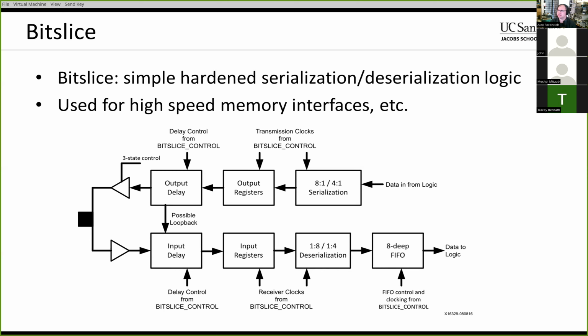This logic is really intended more for things like high-speed memory interfaces, things like DDR4, where you have to run at a few gigabits per second per pin. They're not really intended for asynchronous serial communication like SGMII or 1000BASE-X, but there are some ways of making that work.